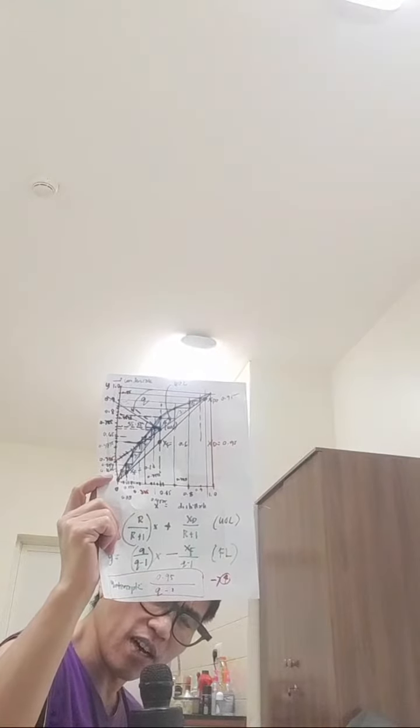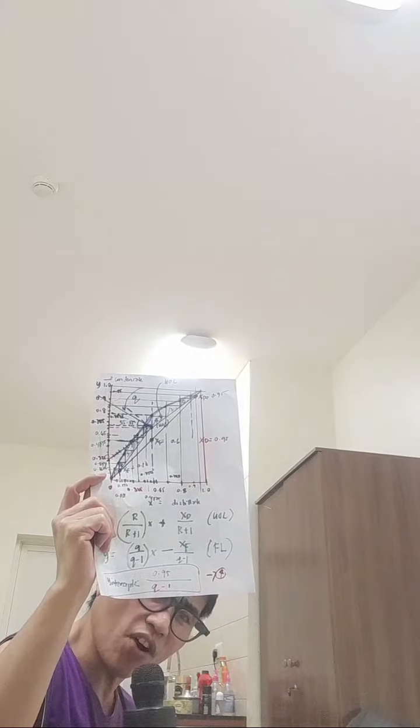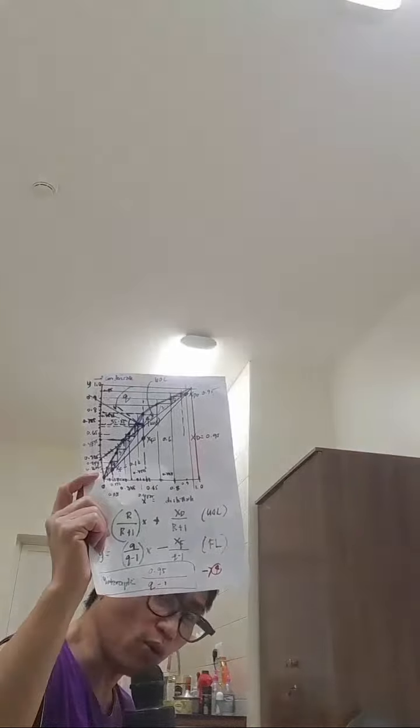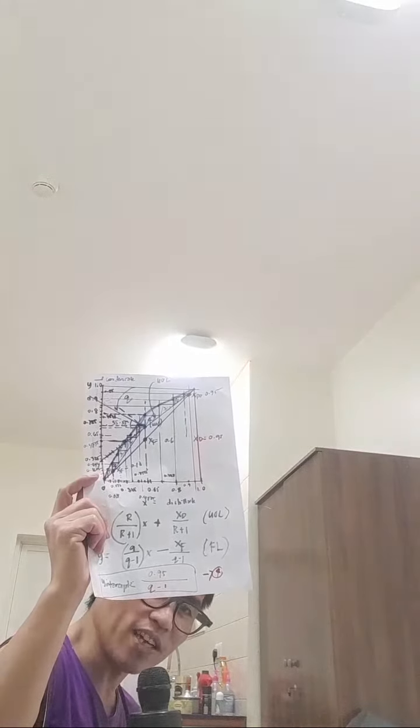It will not go beyond XW. If you put that here, it's a perfect shot, and then it will stop also, because the feed line will intersect there at the value of 0.10, which is logical and realistic. So this is only 8, guys. 8 theoretical plates. Sorry for that. We denote this as capital N, which is the theoretical plates.